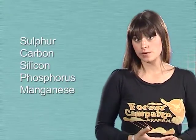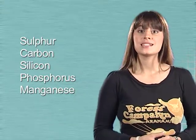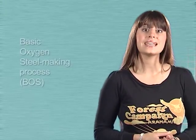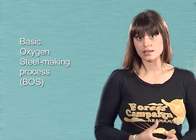It contains sulfur, carbon, silicon, phosphorus, and manganese. Most of the iron produced is used to make steel. Steel is an alloy of iron and carbon and is produced from iron by the basic oxygen steel making process, BOS. This process involves the removal of impurities from the pig iron produced from the blast furnace.